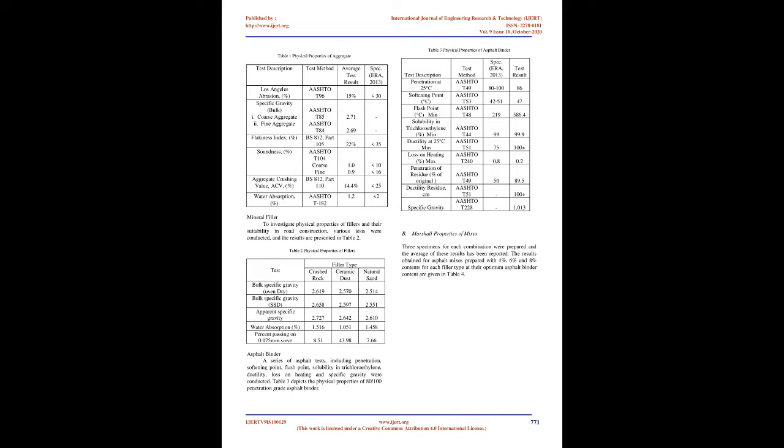22. Pavements are susceptible to low-temperature cracking. Particularly in colder areas, the tensile strength of pavements at low temperature should be adequate enough to resist cracking. Asphalt mixes containing 7% marble dust yield maximum tensile stress, 18.2 kg/cm2, as compared to mixes made with stone dust filler, 9.53 kg/cm2. Thus, marble dust yields better performance in the cold region.